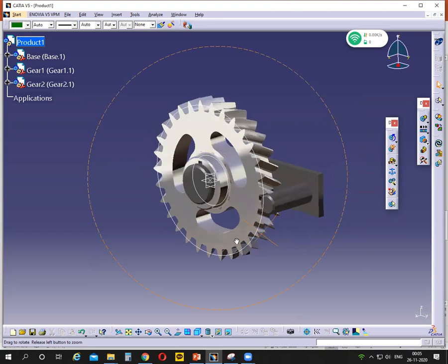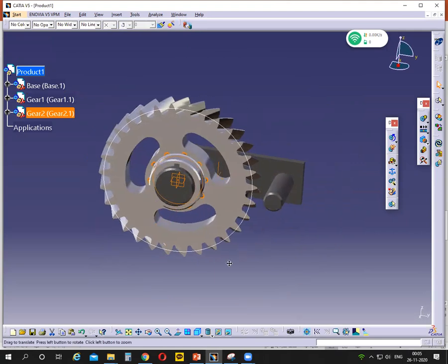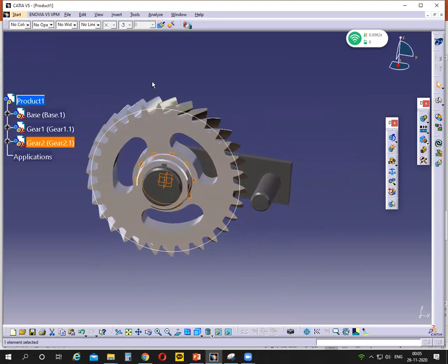Now gear 2 is hiding inside gear 1. We can go to Assembly Design and move that gear. Or if you don't want to move it, no problem: you can just specify this axis and the gear 2 axis as the same, and gear 2 automatically comes here when we select a revolute joint. But if there are many parts, use Assembly Design first.